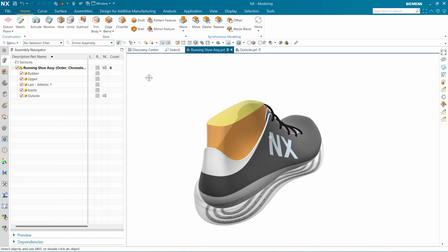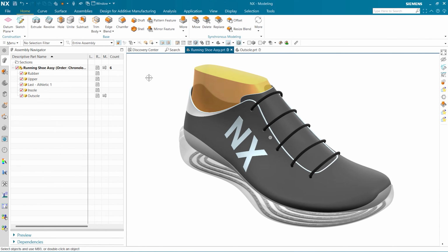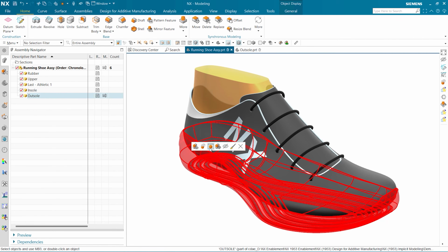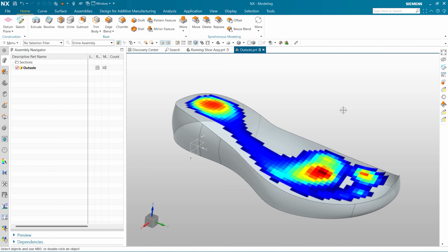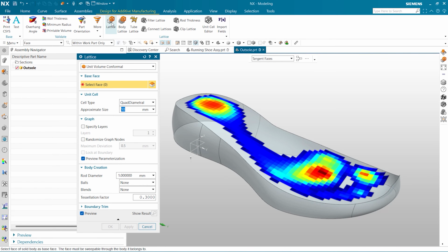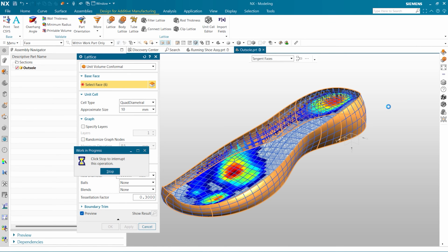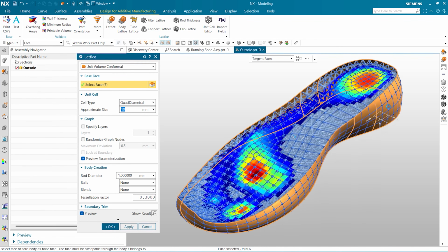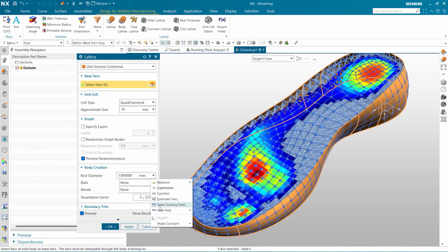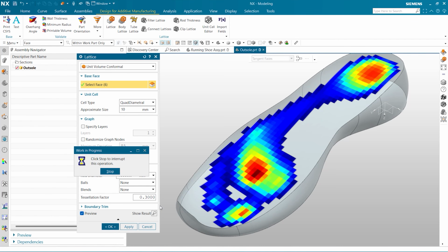Another generative design solution to decrease the mass of a part is to create a lattice structure. This type of structure is also well adapted for additive manufacturing processes, for applications such as shock-absorbing structures, flexible part design, or in the medical industry to facilitate implant-bone integration.